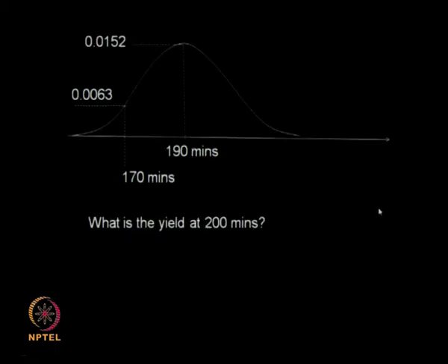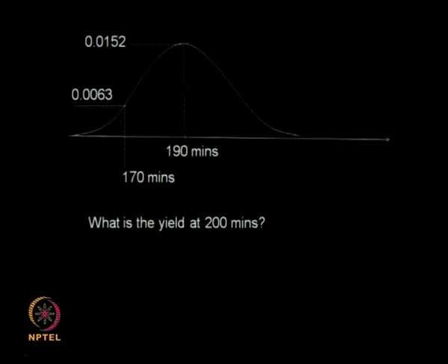Now let us look at another problem where we are going to make use of a concept like yield. So very long time back I introduced something called yield, where if you collect a component between certain times, say time equal to t dash and time equal to t, then we can find out what will be the yield of that particular solute which we have collected. Okay, so that is what we want to calculate here in this particular problem.